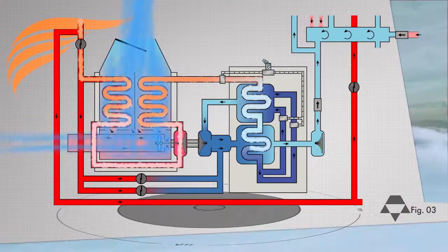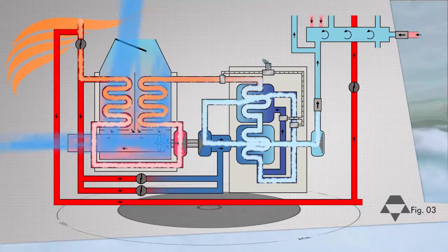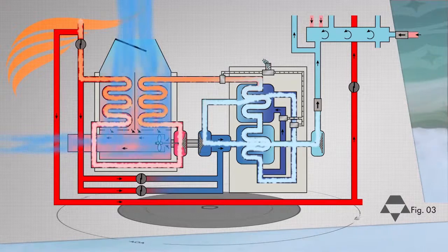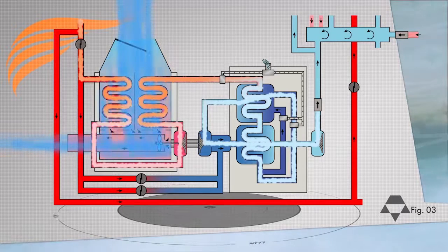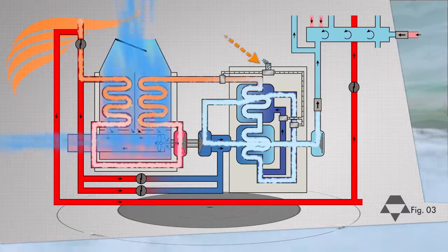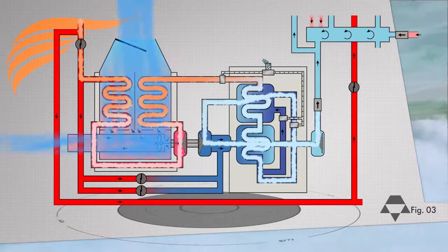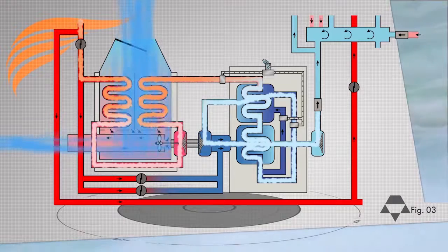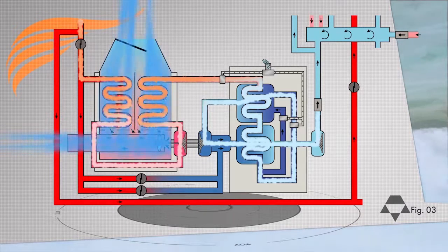Air is then ducted into the condenser and reheater stage. In here is where air flows over both heat exchange cores so that they absorb heat from the air. This temperature decrease induces condensation of moisture in the air into water, so that then a water collector can remove it from the air. During the reheater stage, air is heated once again to add thermal energy to it so that it can later be converted to mechanical energy to operate the turbines in the ACM.